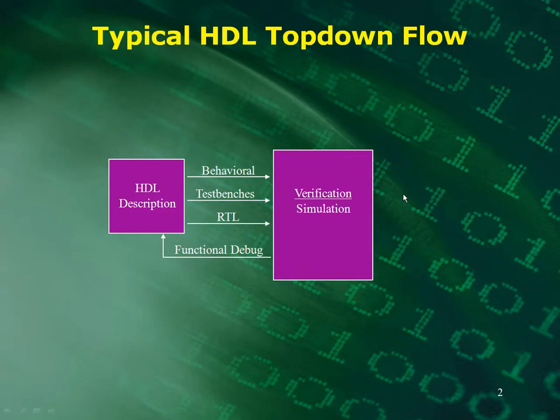Here we have a typical HDL, hardware top-down flow. Here we've written our HDL, hardware description language, descriptions, either as behavioral models or RTL, maybe we've written test benches, and we want to run those through some sort of verification simulation like I was showing you just now.